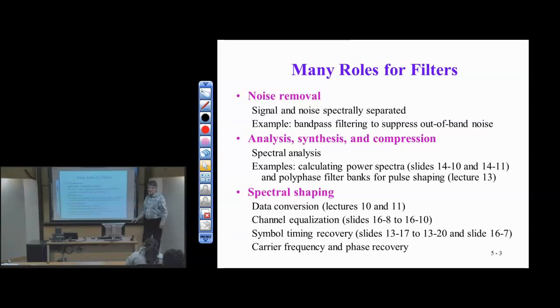The third big picture is spectral shaping. This is the idea that if I have a spectrum and I'd rather have another spectral shape, I can use filtering to change it. A good example of this, let me do a very simple example. Let's say I'm stuck with noise. Okay, so channel equalization is a good example. In a communication receiver, if my communication channel, let's say, is low pass, or just for an example, for bandpass transmission, this would happen in DSL or wireline communications.